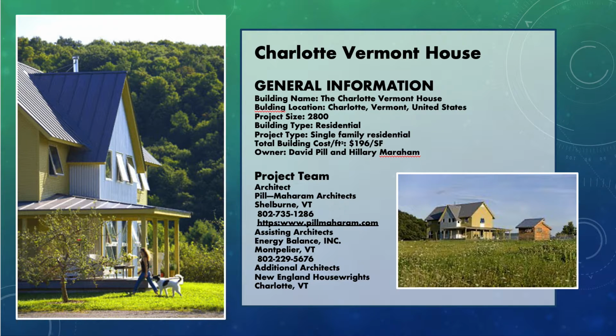The cost ended up being $196 per square foot. So if you multiply that times the project size, you will get the construction cost. That is not the budget cost. The budget will include fees: your fee as a designer, the contractor's fee for building, all his subcontractors' fees. It will include things like permit costs and other things that are part of the process that vary from project to project. So there's miscellaneous other essentials.